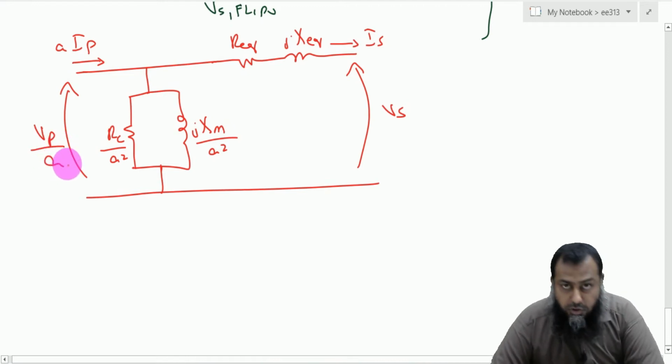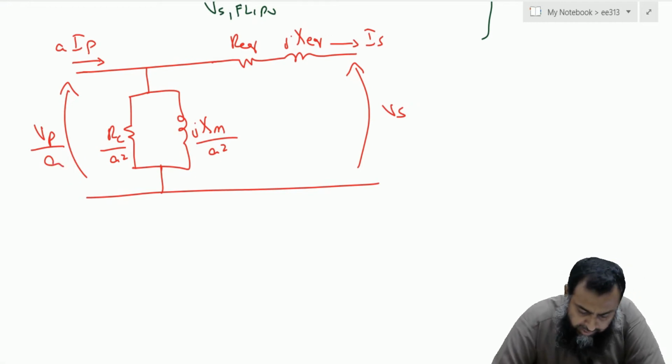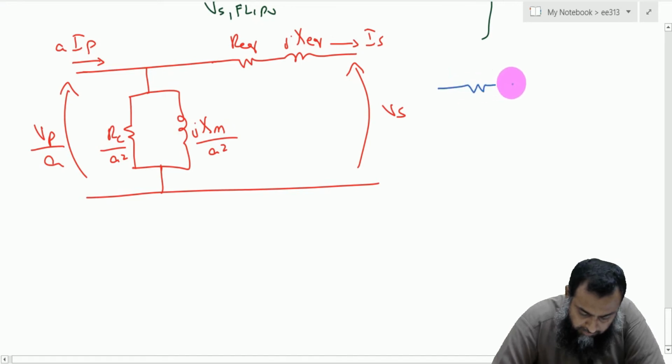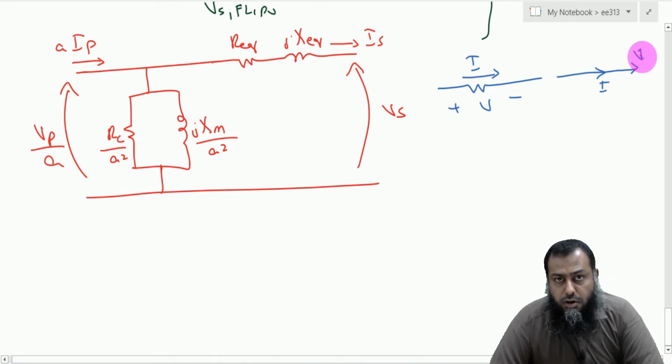Now, to understand the voltage regulation concept in the context of the power factor, we need to use the phasor diagrams. Just for a little revision, if we have an applied voltage V and the current here, then for a resistance, both are in phase, because resistance does not offer any phase difference between the current and the voltage.